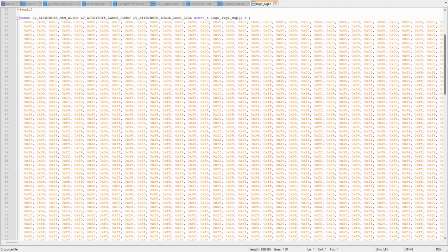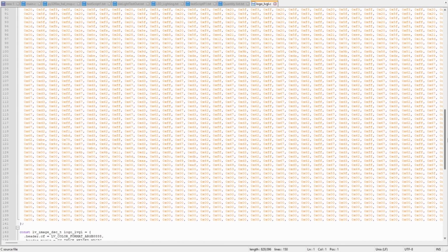As with text, the easiest way to display images is to save uncompressed bitmaps in memory and to move them to the display when you need them. Again, there are online tools that can create these bitmaps. Most photo editors can as well. But the size of these files can really add up. Remember when I mentioned how large a single display buffer can be? You need the same amount of memory for each full-size bitmap.